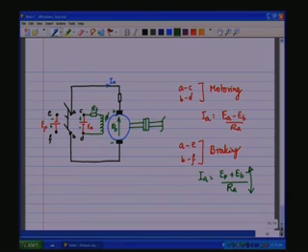and this will try to make the motor rotate in reverse, like applying the armature voltage in reverse, which means it immediately has to come to a stop and then start rotating in reverse. So, when it comes to a stop, you just remove the double pole double throw switch such that IA becomes 0. Now, this can be pretty fast, and this is called plugging.